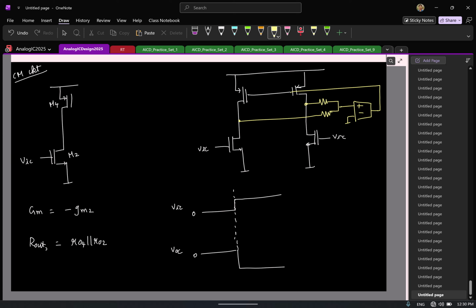So here in the common mode half circuit, I'm going to have a resistor, a GM, right? These two will be put in parallel, so this becomes a single resistor, and then I have the OTA and feedback. And let me look at small signal. So this is grounded, so this also grounded. Again, this is my output common mode, VOC.